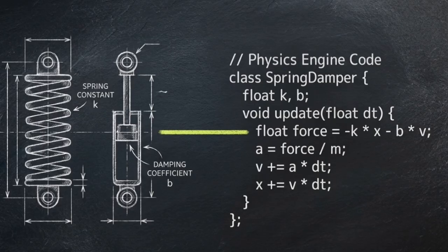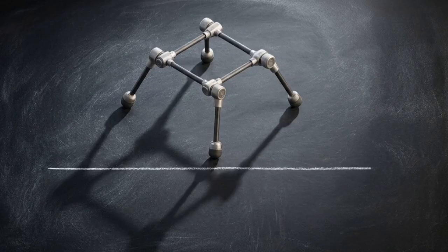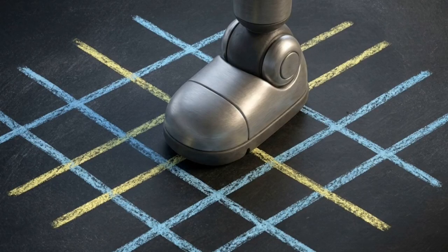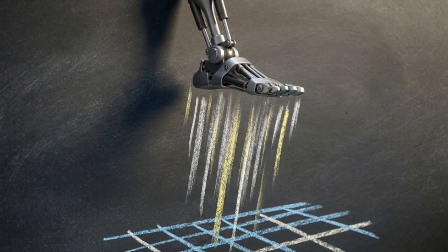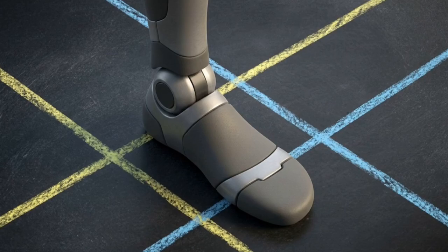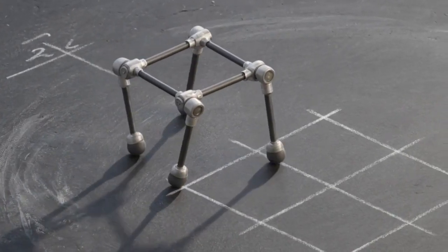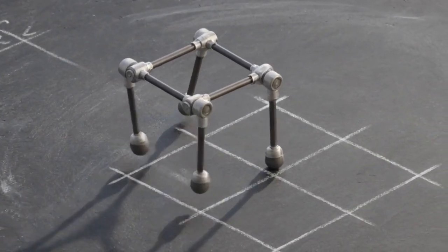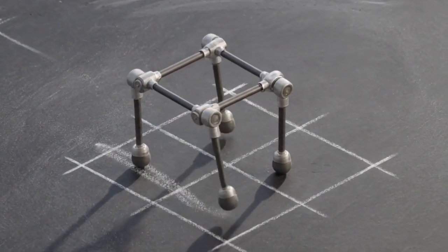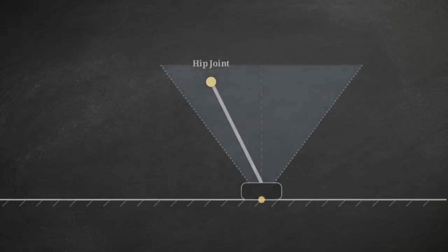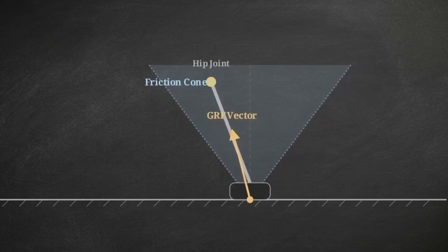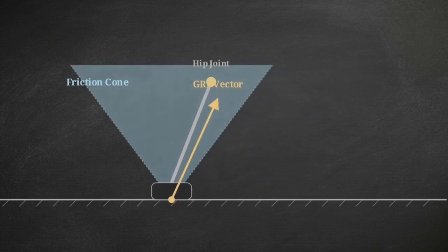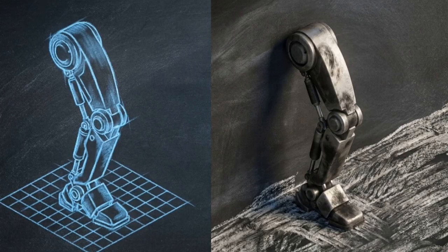Kp and Kd form an exact mathematical bridge. Depending on how you tune them, they dictate whether a robotic foot settles perfectly on the floor, bounces wildly into the air, or sinks through the geometry. When you unite the physical theory of the friction cone with the discrete math of the SDF configuration, you get a fully optimized system. Mechanically, a stable simulation requires keeping all the forces requested by your controller safely inside the Coulomb friction boundary. In software, engineers must consciously anticipate the simulation-to-real gap.